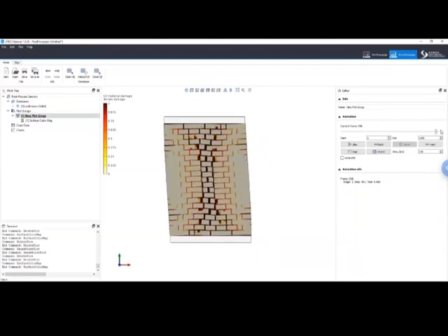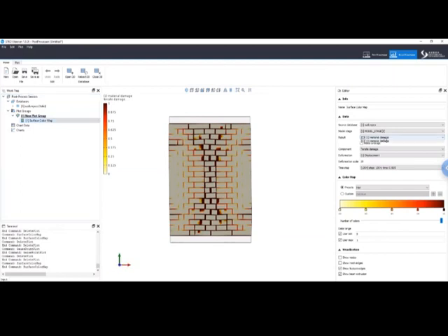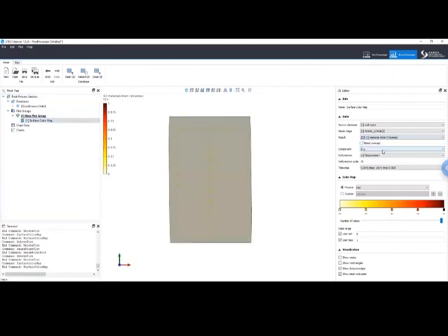So it's fine to visualize the final crack pattern, but if you want to see, like in a cyclic analysis, what is the actual crack that is open, probably the damage is not the best variable. You can use something different, for example, the maximum tensile strain. So you can go under here, principal max, and let's say, now, don't put a limit to this one, okay?